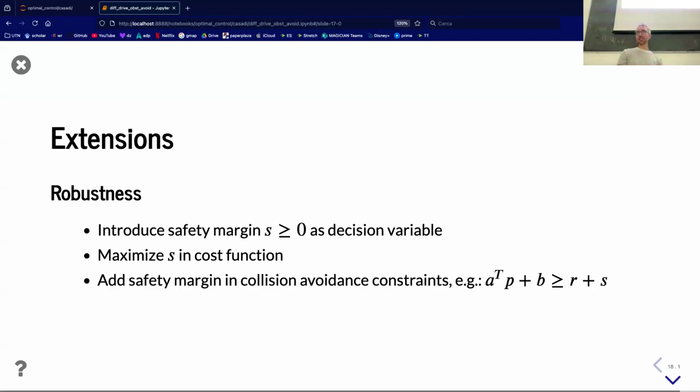That's not ideal in terms of robustness, because even if we extended it to have really no collision in continuous time, then if you go and execute that trajectory on a real robot, you're going to have some noise, some small deviations from the reference trajectory which we compute. And what might happen is that the robot hits the obstacle because we have no safety margin. So one thing one could do is, well, I can just make my obstacles a bit bigger, or make my robot a bit bigger, it works the same, so that I have a safety margin.